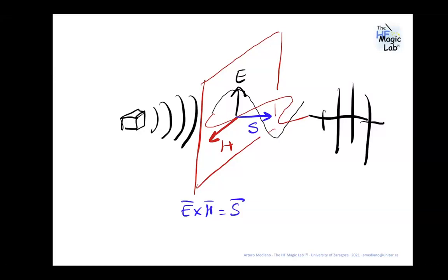Can you use a circular antenna and receive all the polarities? Yes, but you will not be able to identify if the polarization is vertical or horizontal. This is very useful, because it is a very good clue to identify if the emissions are coming from horizontal cables, vertical cables, horizontal slots, or vertical slots. With another kind of antenna you will see the signal, but you will not be able to make debugging in the same way.